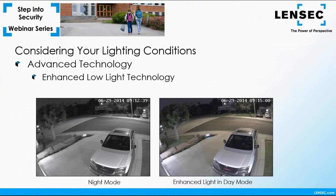Compared with any analog or network cameras, the light enhancement will give more lifelike colors in low light conditions. Noise reduction is vastly improved compared with standard surveillance cameras. In fact, these newer cameras can provide color images in nearly no light at all. The display seen on the left is using a camera that has switched over to night mode. The picture on the right is using a camera with light finder technology, which is still functioning in daytime mode. You can see this will provide a color image and details with excellent clarity, even though it's night outside.